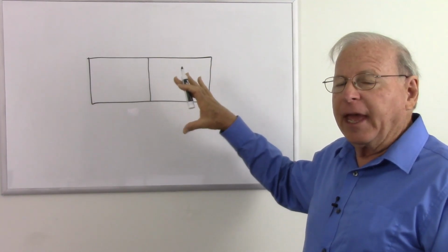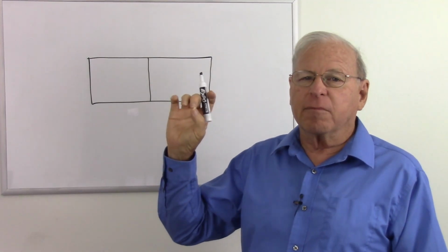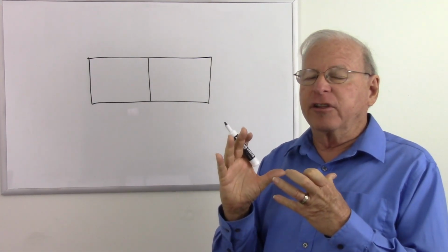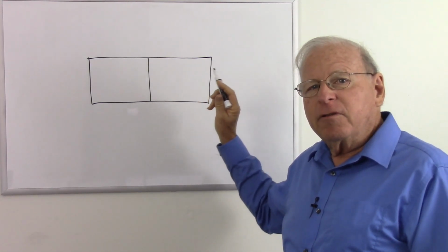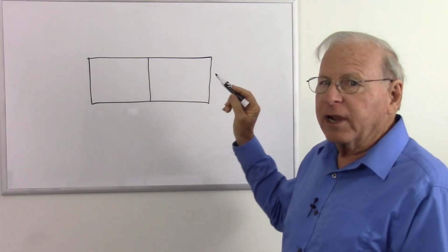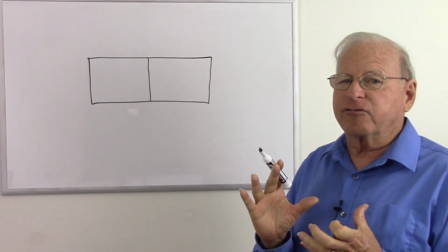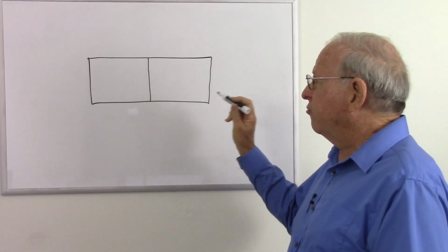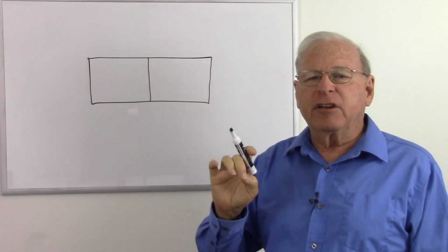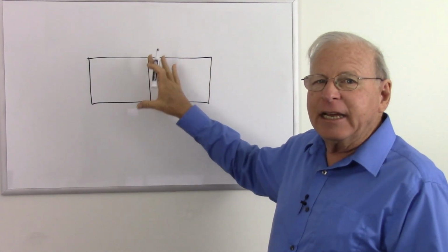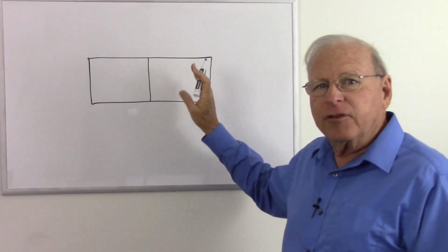Silicon and germanium have 4 electrons in the valence shell, and they form a covalent bond, a very strong bond that binds the electrons into the crystal structure very strongly, so they are non-conductive. But if we put just a few atoms of arsenic or antimony, or anything else that has 5 electrons in the valence shell, there will be an extra electron for every atom we put in there. Those extra electrons don't fit into the crystal structure, and so they tend to float around. They want to remain near their atoms, but they can move around rather freely, so it becomes conductive.